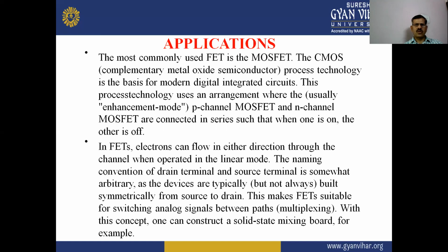So the most commonly used FET is the MOSFET. The CMOS, complementary metal oxide semiconductor, process technology is the basis for modern digital integrated circuits. This process technology uses an arrangement where the usually enhancement mode P-channel MOSFET and N-channel MOSFET are connected in series such that when one is on, the other is in the off state.